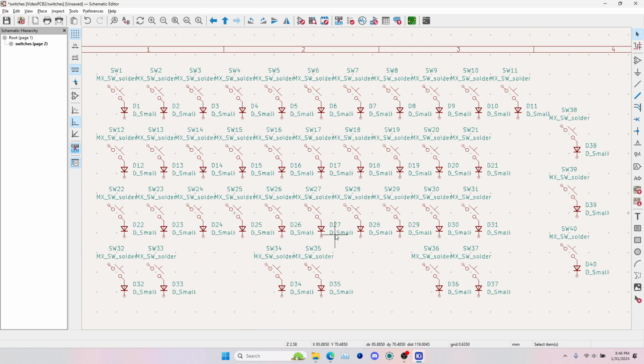So the KLE Placer plugin, it reads from left to right, and you can read the notes on the GitHub README for that plugin. But what that essentially means is we want our keys in the schematic to be numbered as you read it left to right, and increasing. So that's 11, and then if you read the next row, well, this would be 12, but actually there's a key above it, so that should be 12. Then 13, 14, and that's 23 at that point, I think.